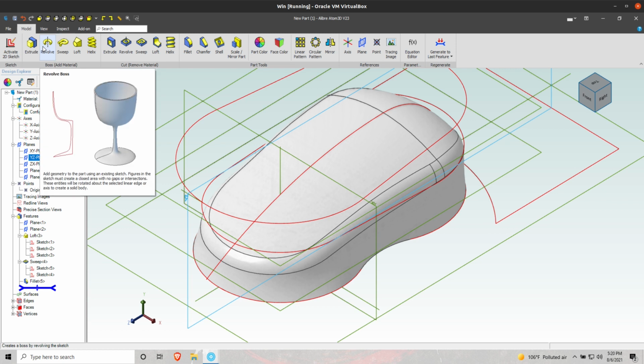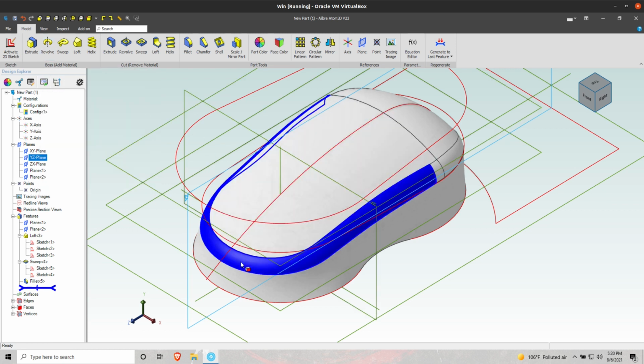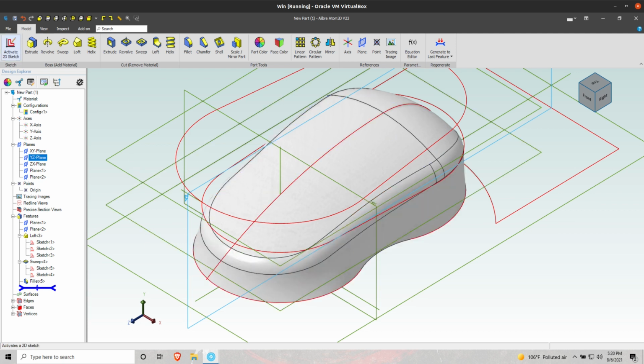Normally you save your fillets till the very end. I feel like this fillet could be affecting other features, and so I want to make sure that I add the features with the fillet so that I can know that everything will work with the final geometry.